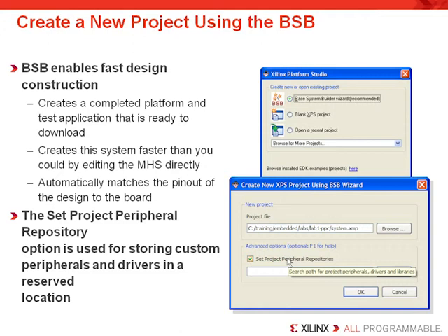The Base System Builder will also generate a UCF file which contains your final pin assignments and pin attributes as well as timing constraints for your demo board. Now it is a standard file used in all FPGA designs. Like the MHS, I encourage designers to open this file as well and review its contents. Like the MHS, it is user editable, but is easier to change when you use the Xilinx Constraints Editor. But that is accessible from the ISE tools, not from within EDK.